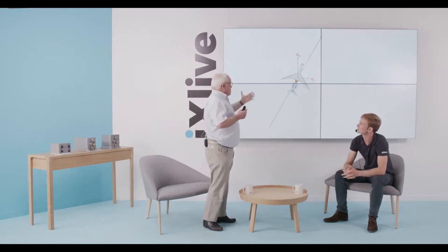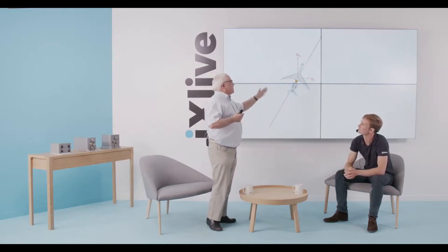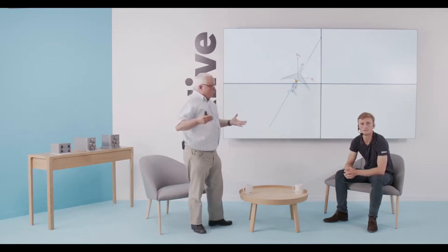So it means that in that case, with a straight line at constant speed, the heading will drift the same way it's drifting when we don't have the GNSS information. The good thing about this is that still the velocity and position will remain accurate, because it comes from the accuracy of the GNSS, but heading will drift.